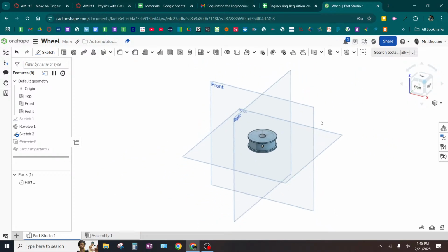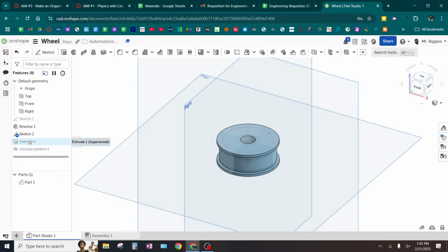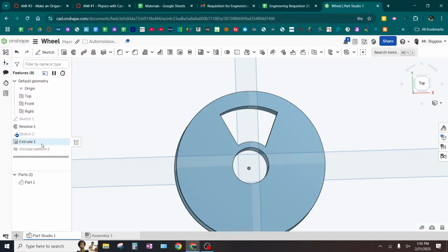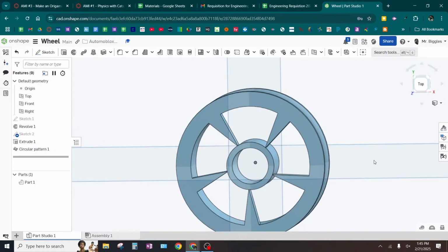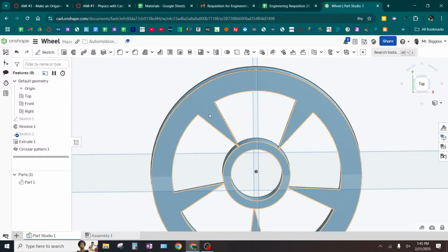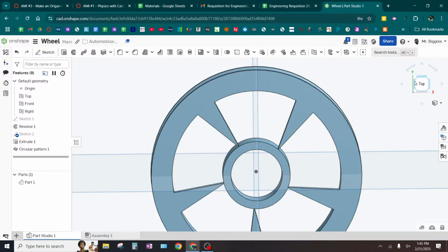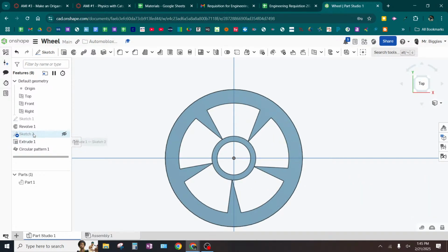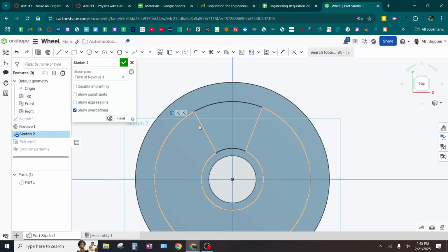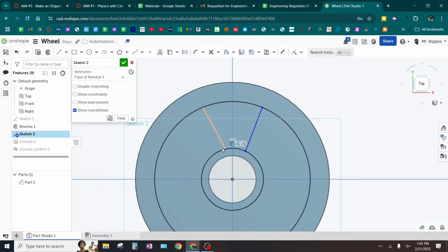All right. So yesterday, I did a quick little demonstration of something. I did this cutout here, and then I circle patterned it. And I did it really quick. But the point that I wanted to make is if you don't do this intelligently, what can happen is you get spokes like this, where the thickness of the spoke changes. So imagine that I did my spokes as parts of a pizza slice, okay? So imagine this is basically part of a pizza slice, all right?